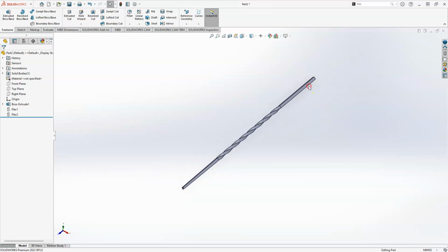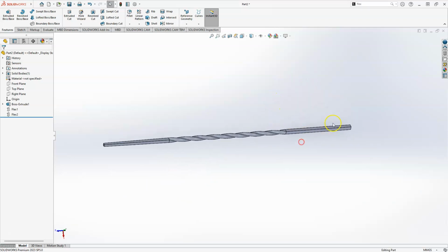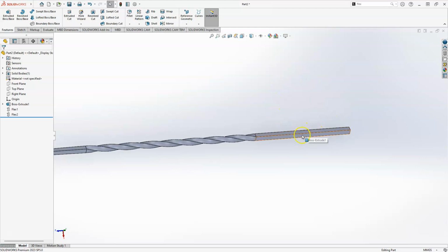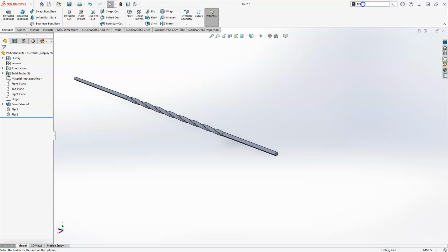Okay, I would like to bend the entire profile from, let's say, half of this one, which would be the 50 millimeter here. Let's select Flex one more time.